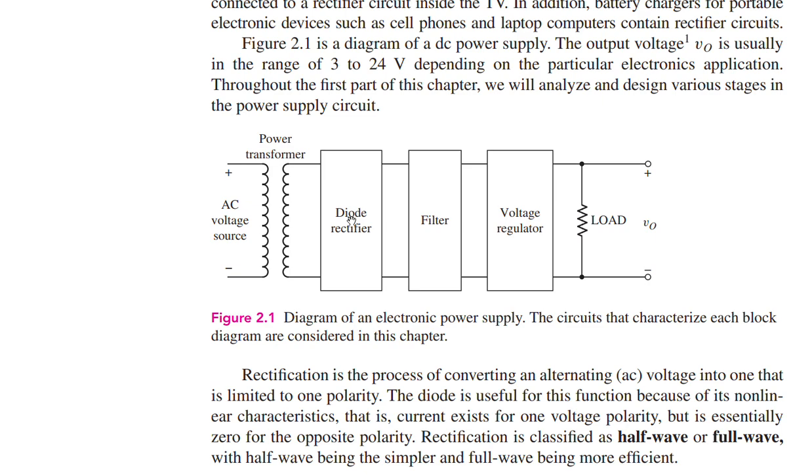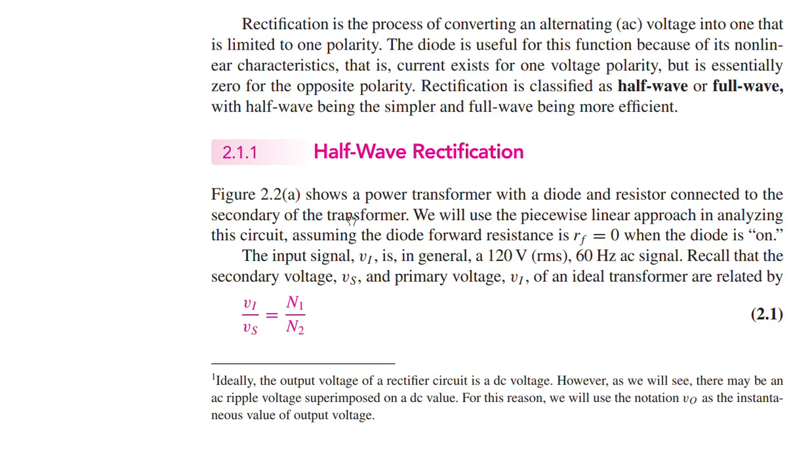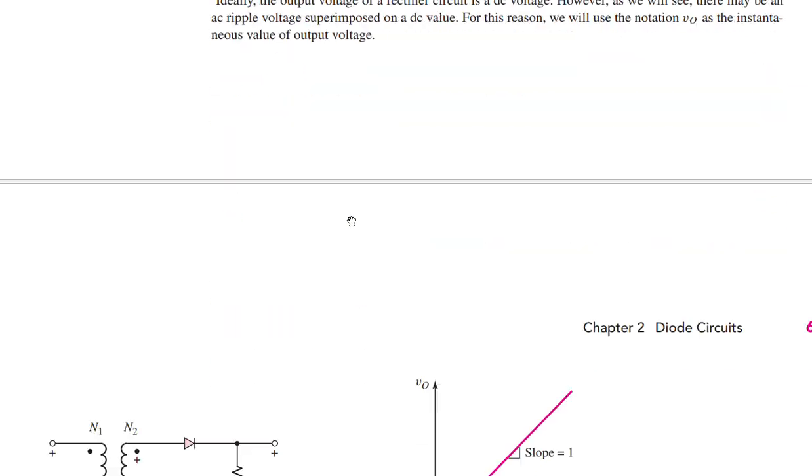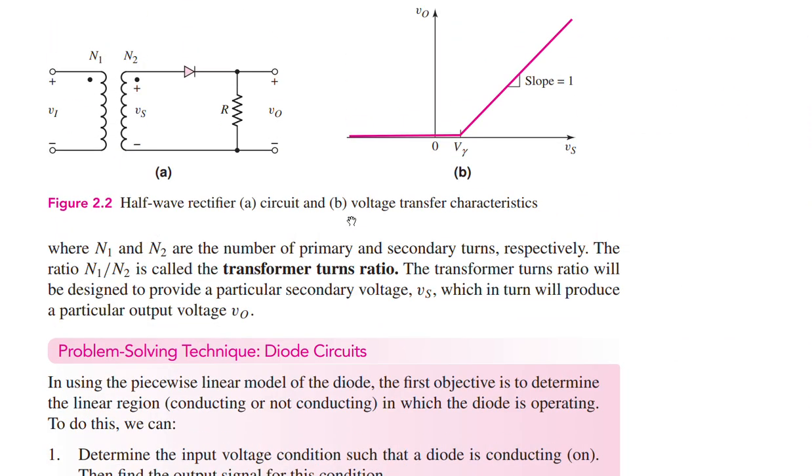That was a half-wave rectifier. We did some derivations for the half-wave rectifier. One part that was not covered was the peak inverse voltage. Peak inverse voltage basically means that if the diode is reverse biased, what is the largest negative voltage that can appear across the diode? Like if we talk about the forward bias voltage, we are taking the difference of the voltage on the anode side with the voltage on the cathode side, which is typically in forward bias a positive value equal to V gamma, which is roughly 0.6 or 0.7.